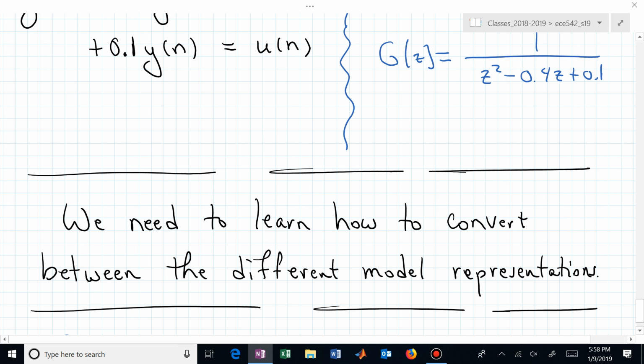Realize that in this class you're going to have to figure out how we connect all of those pieces and parts. If somebody gives me a third order differential equation, how can I control that system? Oh, maybe I want to put that into a g of s. You need to figure out how to find a g of s. Now what do we do? Well, maybe now we need to figure out how I take a g of s and obtain a g of z from it? And we'll talk about finding discrete equivalence.